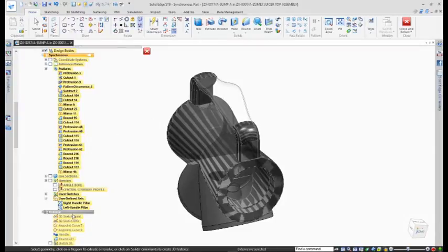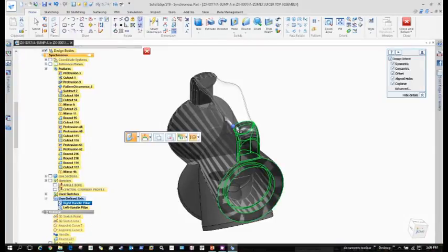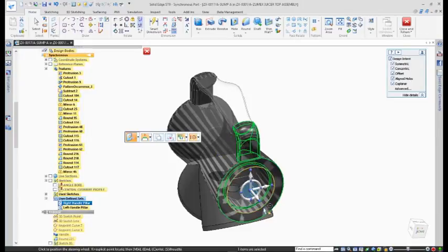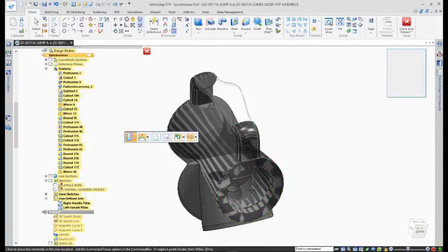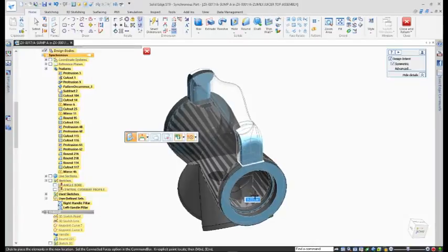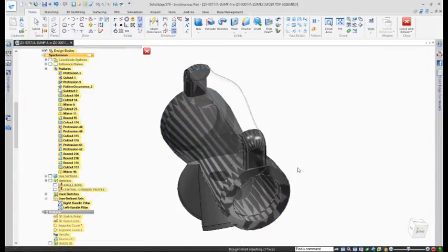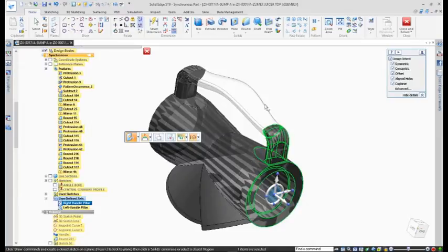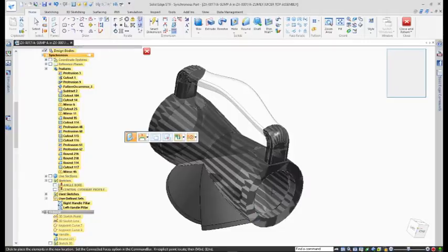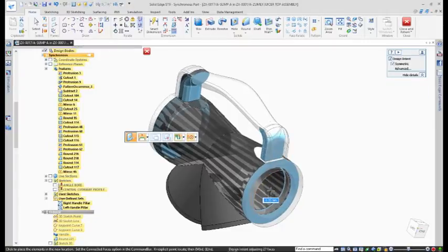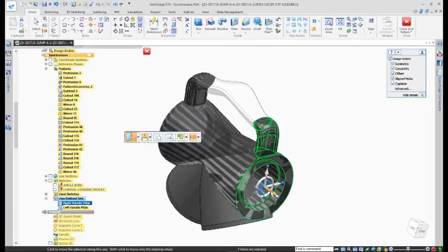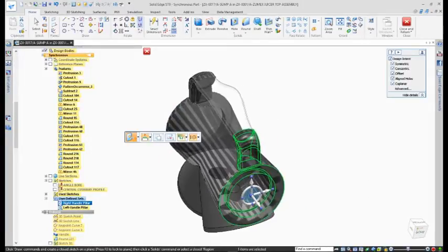What that means for us is that we can now make edits while inside the synchronous header, without any fear of not knowing what's going on. So in this case, I'll pull out 15 millimeters, and you can see how even the ghosted geometry updates. So that's pretty cool. Let's put it back. Put this guy back 15. And once again, you can see the changes. I thought it was worth showing again.